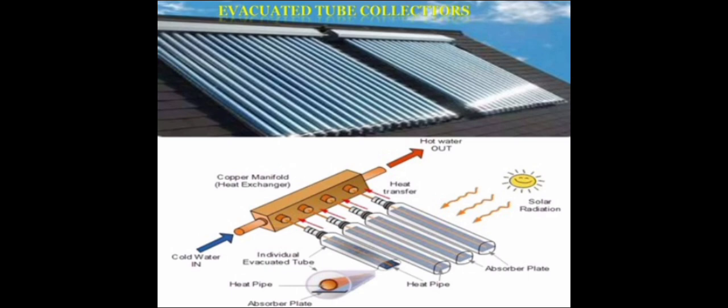These glass tubes are cylindrical in shape, therefore, the angle of the sunlight is always perpendicular to the heat absorbing tubes, which enables these collectors to perform well even when the sunlight is low, such as when it is early in the morning or late in the afternoon, or when shaded by clouds. Evacuated tube collectors are particularly useful in areas with cold, cloudy wintry weather.